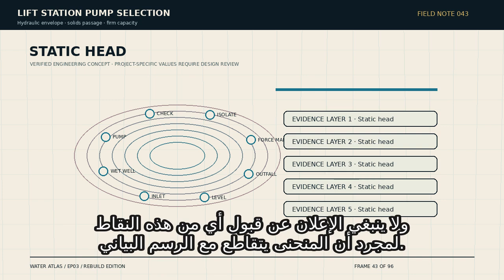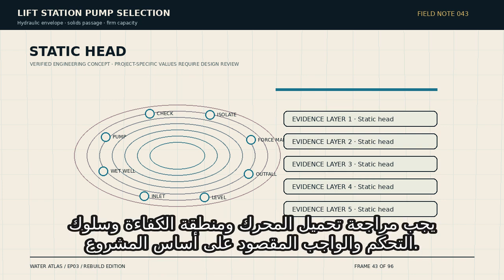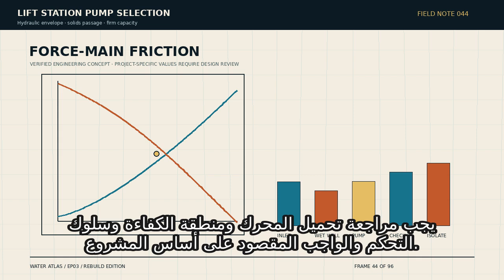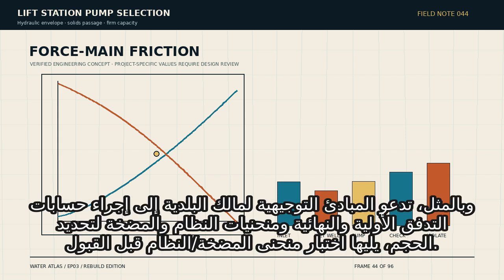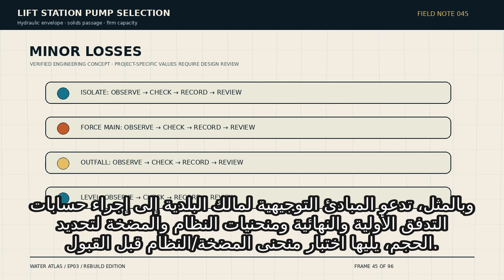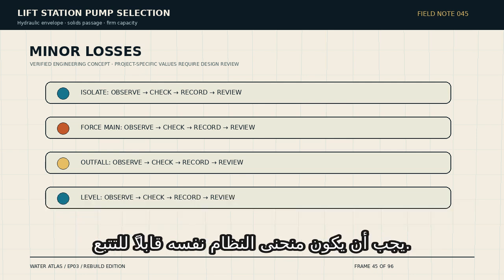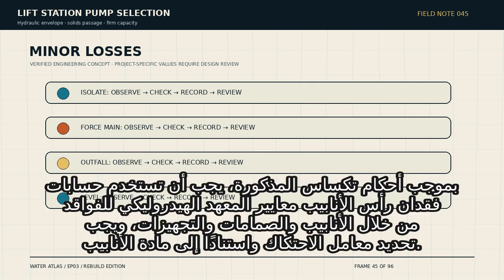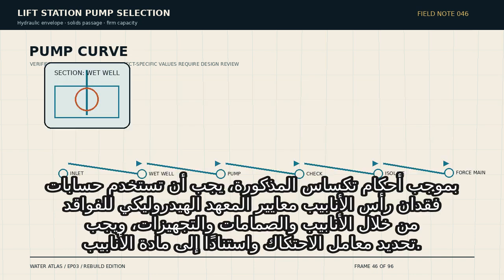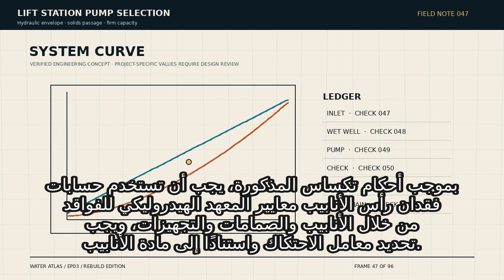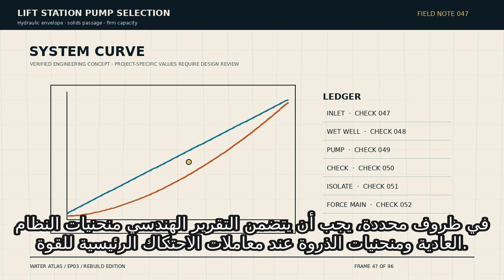The system curve itself must be traceable. Under cited Texas provisions, pipe head loss calculations are to use Hydraulic Institute standards for losses through pipes, valves, and fittings, and the friction coefficient must be identified and based on the pipe material. In specified circumstances, the engineering report must include normal and peak system curves at applicable force main friction coefficients. That is a jurisdiction-specific requirement, not a universal instruction for every lift station. The broader design principle is universal in practice. Record the method, material basis, units, and operating cases so another engineer can reproduce the decision.